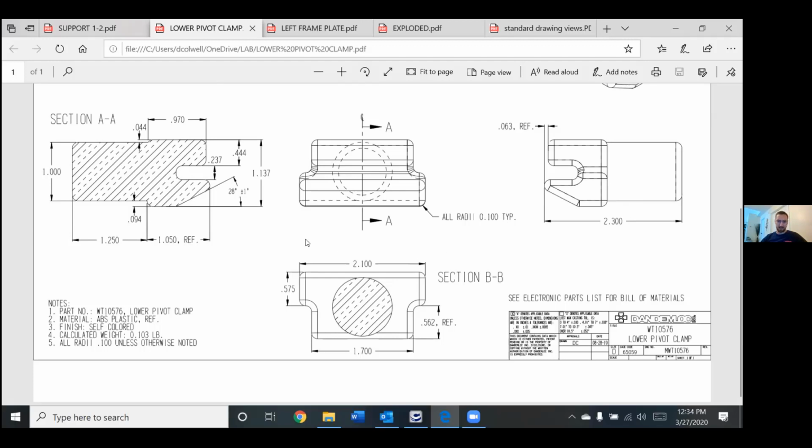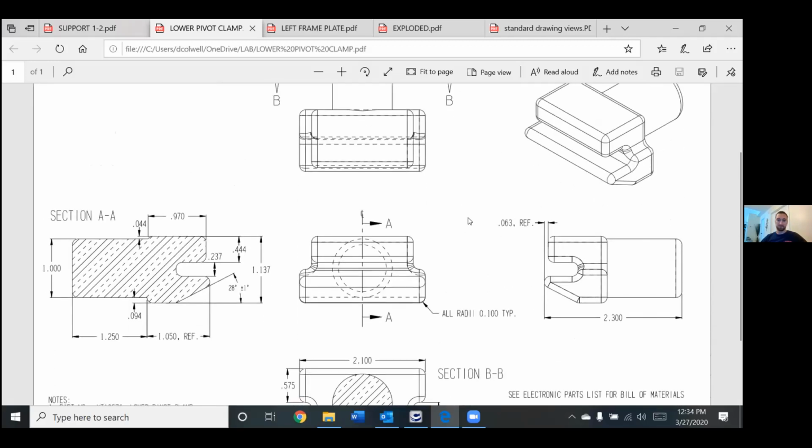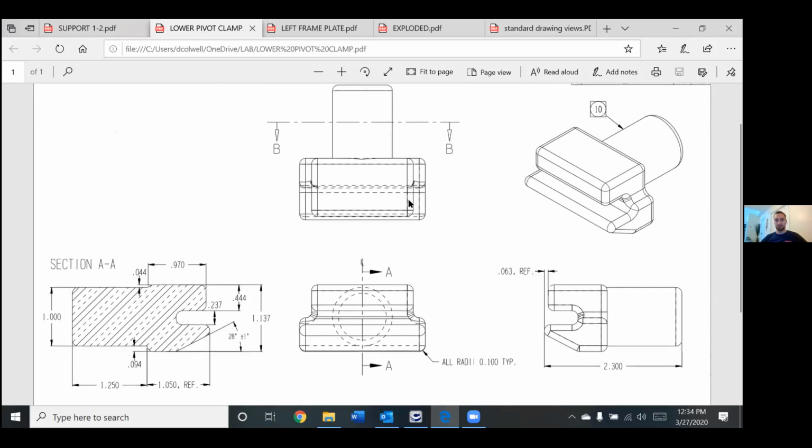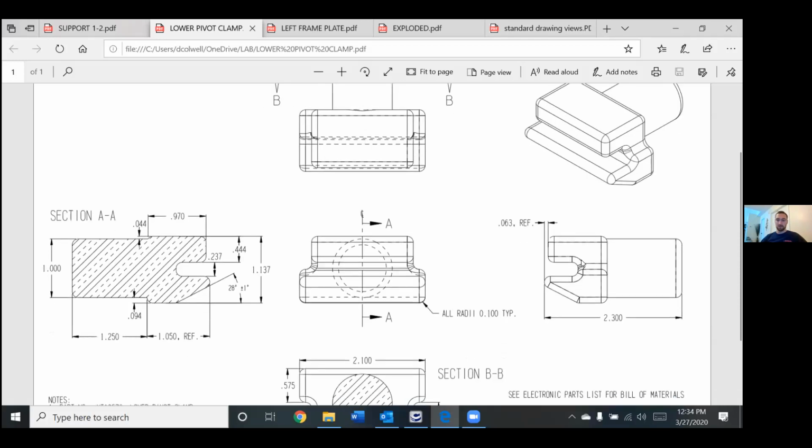Let's see. So we have the bottom view here, which is actually a section view, and it's sectioned from up top here. Notice all these hidden lines. There's nothing dimensioned on this, but if you were trying to dimension things here, you would probably want to remove some of these hidden lines. But since they're not hurting anything, they're still on there. Get your isometric view. Again, this is a reference dimension just because it has been stated somewhere else. Basically, what that means is all these things would add up to those dimensions, and so saying it over here is sort of redundant.